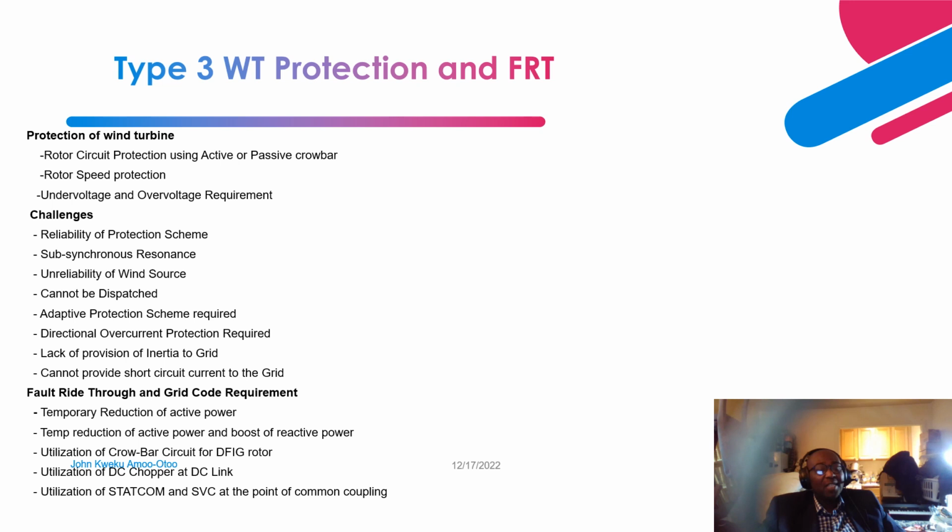So if you have an existing XL, that is the reactance of the transmission line, having a decrement minus XC due to the installation of series capacitance. So overall, in the denominator, your X decreases. That basically helps to increase the amount of power that is being transmitted, right?